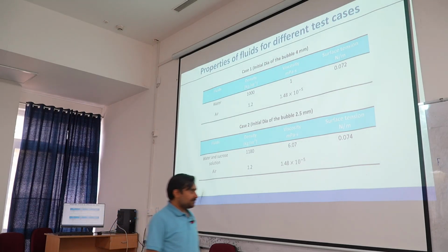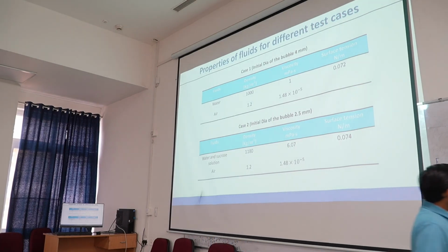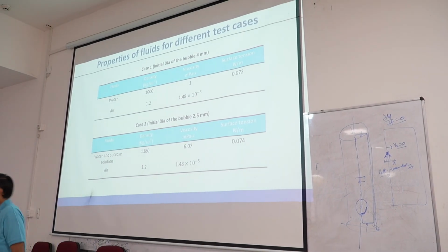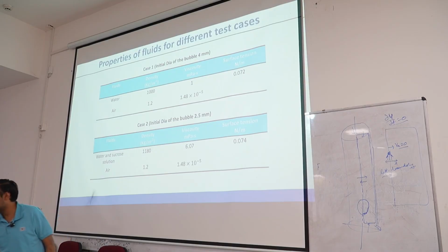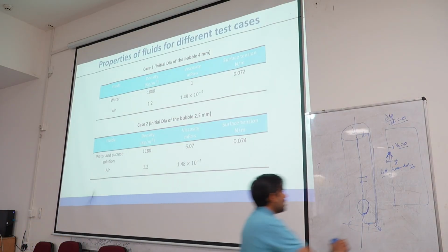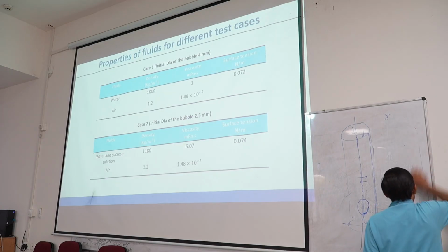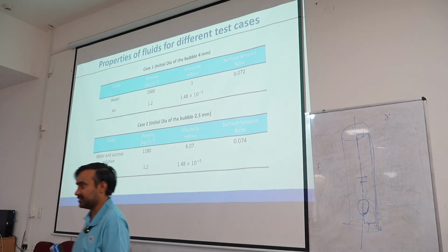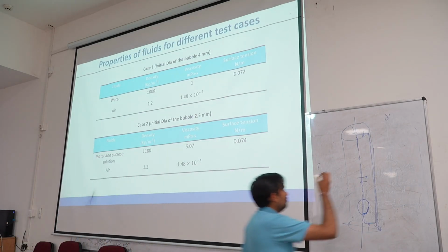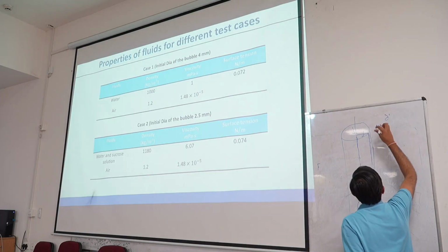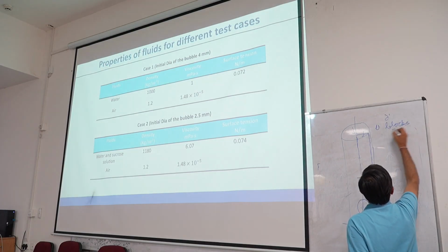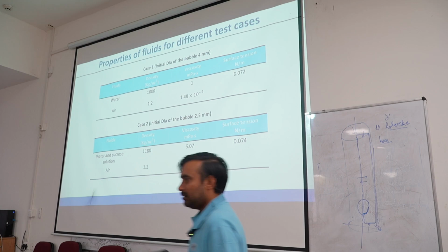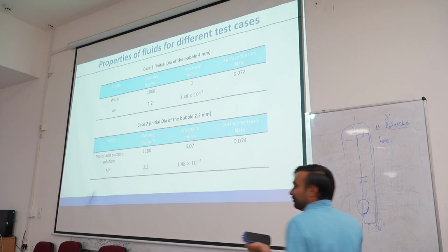So, that is the reason whenever we define the mesh for an axisymmetric domain, OpenFOAM actually uses the same blockMesh dictionary. It uses the same utility for defining the mesh, the same utility which is typically used for a 3-dimensional case. In that utility, when we define different blocks, we use one command, hex. So, we define hexahedra. But in an axisymmetric case, we will not be having full hexahedra.